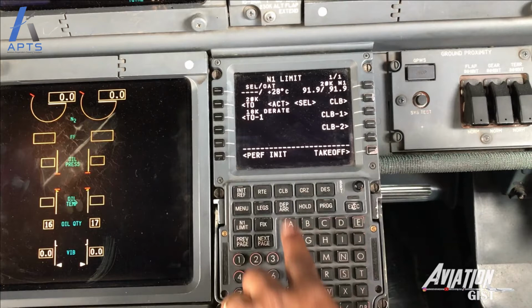Enter the temperature using a /, then the temperature into the L1 select key. In this case, the reported temperature is 28 degrees. The remaining requirements for this page will be completed when the load sheet is received and values received computed against the associated aircraft performance analysis table. More light will be shed on this in a different lesson.